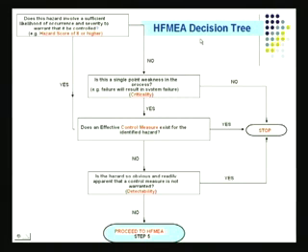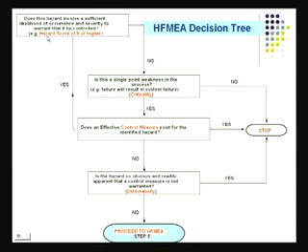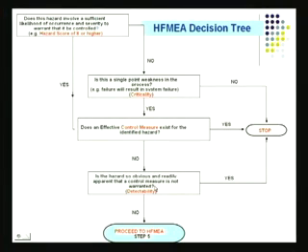So what it says is, let's say first you've done this, and then you've got a number there. If the hazard score is 8 or higher, you move this way and see, does a control measure exist for the identified hazard? If it does, you've got your action done. You don't really have to go further, just activate that action. If it does not, then you see if you could improve the detectability of that particular thing, and then you proceed to what we call a hazard guided FMEA. This is something that you should be doing.